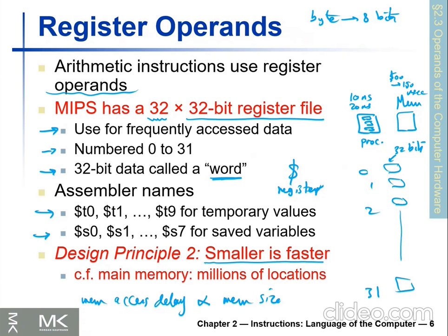But if you have 16 registers, yes, accessing registers will have less delay, for example from 10 nanoseconds to 1 nanosecond. But now, with 32 variables, 16 of them must be in the memory, and to access one of them you're going to have, for example, 100 nanoseconds. So it's a trade-off.